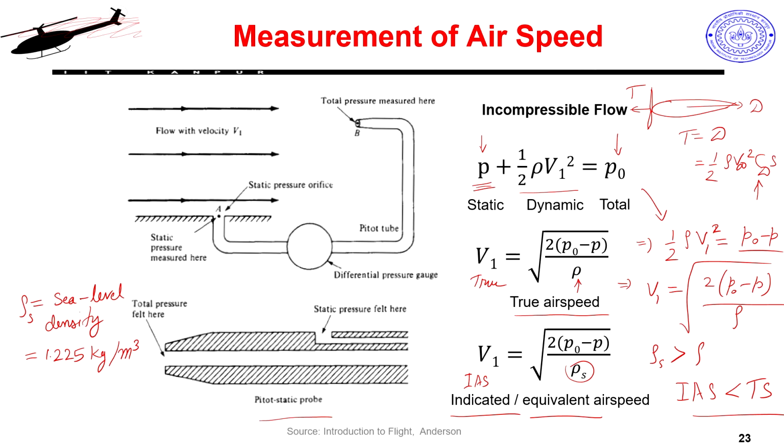How? No, I am talking about ground speed. My UAV speed with respect to earth, how do I get that? GPS, not IMU, GPS, right. Or GNSS to be more precise. So, every UAV is getting navigated through an INS plus a GPS or GNSS system, right. So, your GNSS system is doing the localization and positioning, and the rate of change of position will give you the speed.